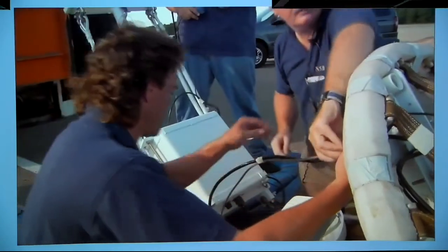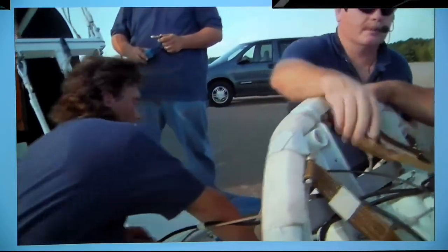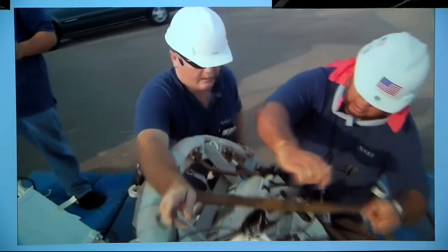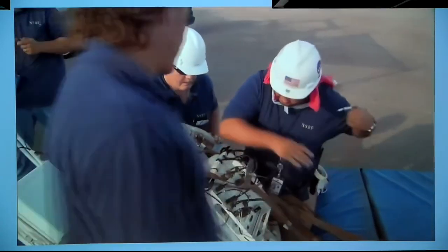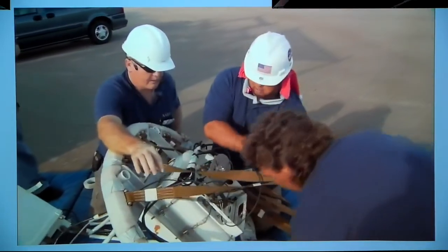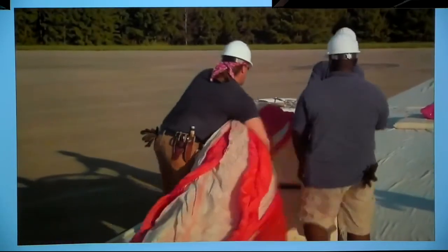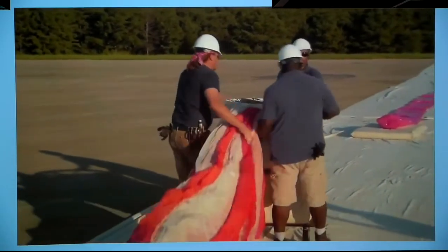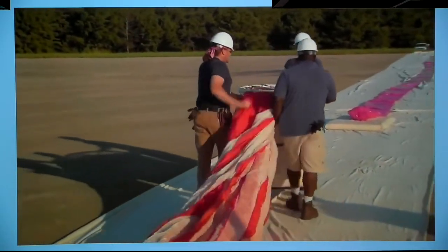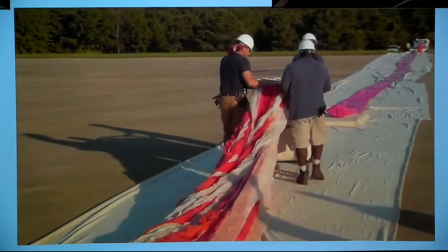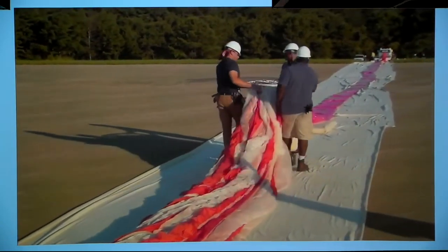Rotator should be on. This unit separates the parachute from the payload to prevent a wind-filled parachute from dragging and damaging the payload after termination. The nylon parachutes range in size from 46 feet to 159 feet in diameter for the largest payloads. And then we'll have the terminate fitting, which is the link between the parachute and the balloon.